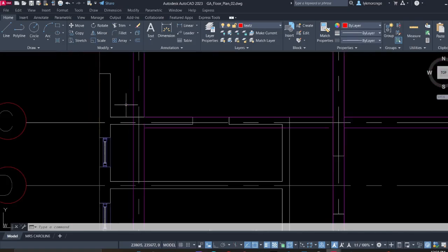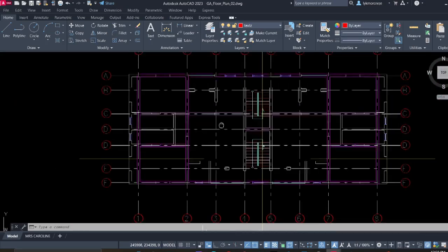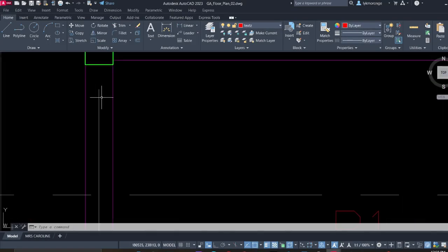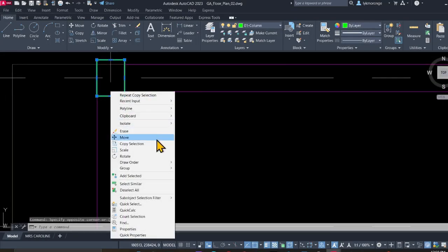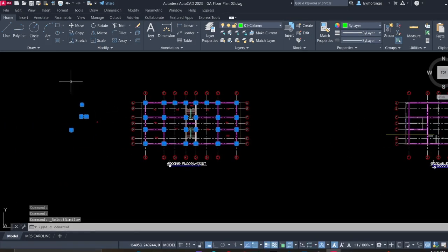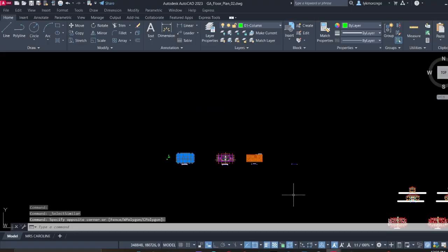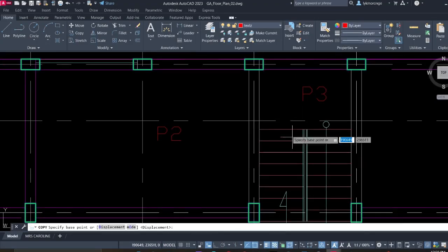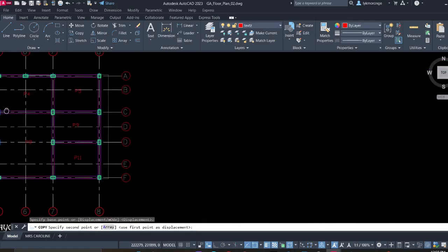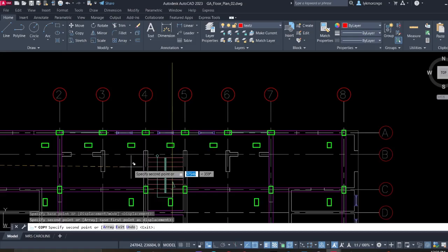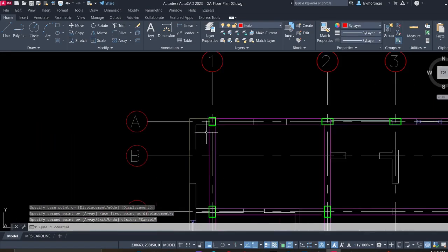So to do that, we simply come to this one here, and remember also that to copy the beams, you can also copy the columns as well. So right click here, select similar. When you have these columns, right click, copy, pick them at the same points of intersection. So just bring our columns up to these points, and now we have it. You can see how our model is, and there is this extension of the cantilever. So we want to sort out this one first.